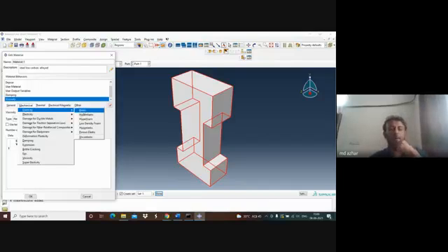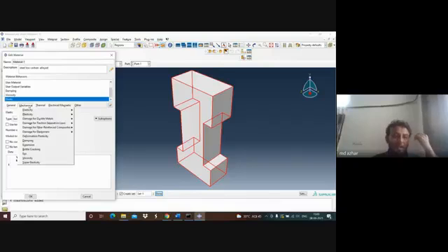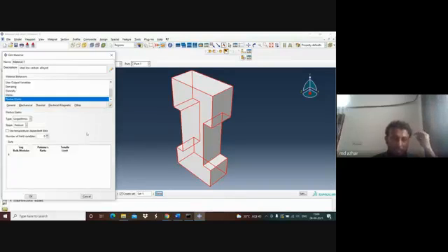So you have the elastic properties, with simple Young's modulus and Poisson's ratio. Here it is mentioned no compression and no tension. No compression, no tension means everything has to be the same. Okay, and your Young's modulus and Poisson's ratio will be the same in compression as well as in tension. Then you will have the elasticity here. Then you'll have different kinds of elasticity. One is the porous elastic model.